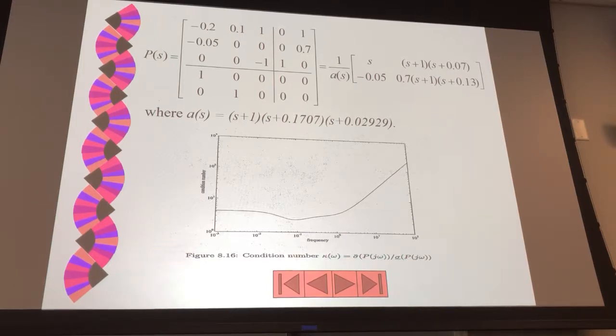So the reason we show this one to you is you have two orders of magnitude difference. Okay? The minimum is here, the maximum is here. 2, 3 orders of magnitude difference. That probably is not a very good sign. You need to take care of such a wide range of conditions. That condition number probably will tell you how hard the system is to control.